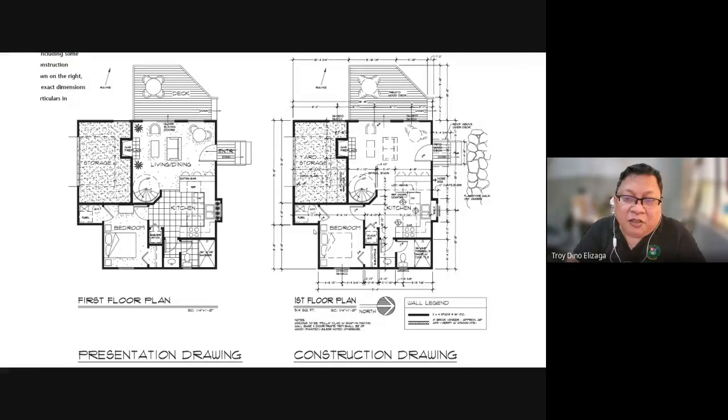On the other hand, the construction drawing is meant for contractors, the builders. If you notice the furniture this time, the sala set, and also in the bedroom, they are drawn in hidden lines because anything that you draw here will have to be built. If you draw them in solid, it means that the contractor has to provide the sofa, the chair, and the coffee table. But you just wanted to indicate that this furniture will be placed here. So at least that's a consideration when they work.